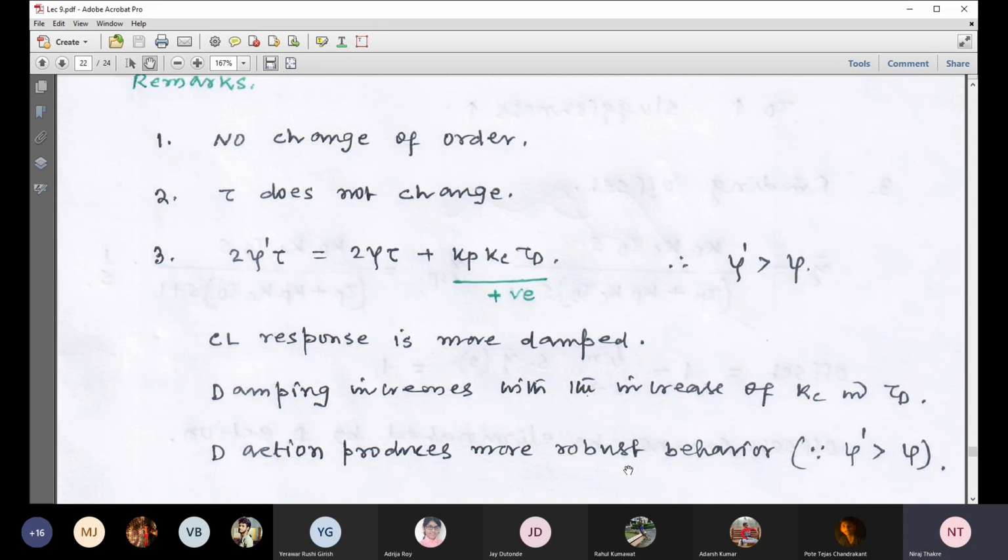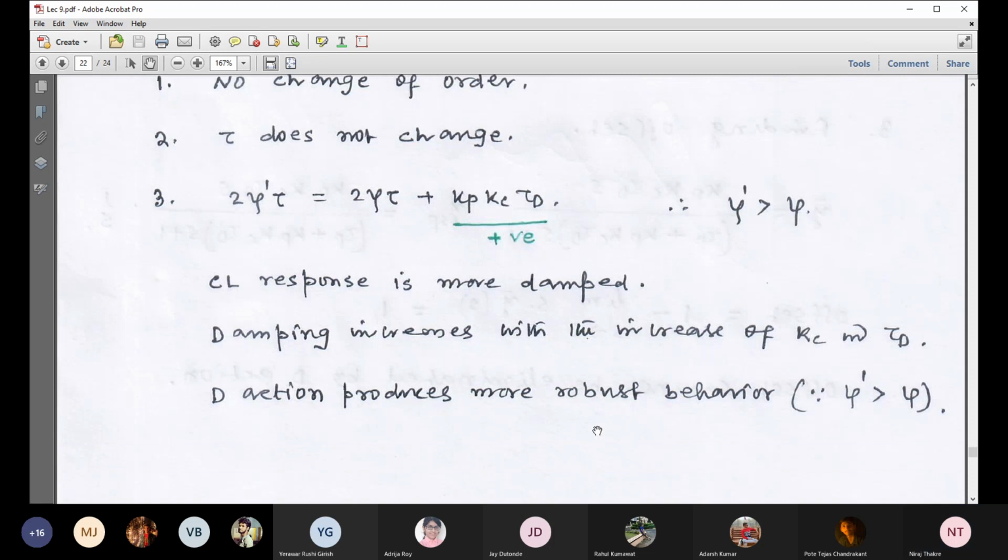Two steps forward movement for proportional and integral action, one step backward movement for derivative action. So derivative action is a conservative control action, and therefore this term is used, robust control scheme. So this is all about the effect of three actions.